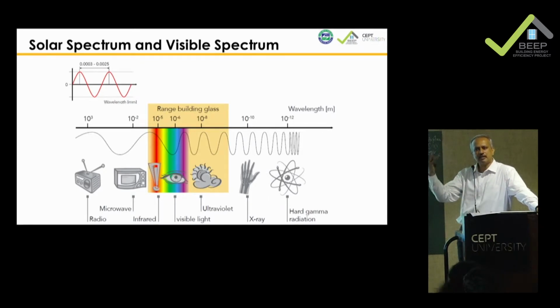So when you have solar radiation, it's like the greenhouse effect. Solar radiation gets through the glass, hits the surface, changes the frequency, loses its strength to get out of the glass, and hence it becomes warm inside. And that is what we call the greenhouse effect. Right? So what we receive, when we deal with the fenestration, we probably need to deal with from here to here. When we deal with the daylight, Gurneet will talk about daylight, we will deal with only this much, because that's what we see. Okay? So this is where daylighting is different from solar radiation.